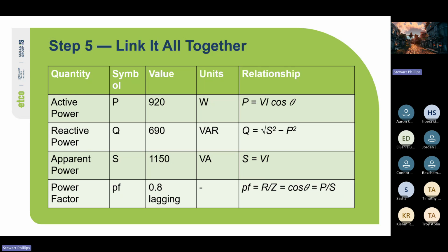We always need to remember when we're doing active power, it's watts. It's the actual work being done. Whereas reactive power is our volt amps reactive, the total voltage and current being used up by the reactive component. And our VA, or volt amps, is our apparent power, which is the total power being sent to our load. It is also what we are usually billed for when it comes to power. Does anyone need more time to write that down, or shall we move on? Cool, sweet.